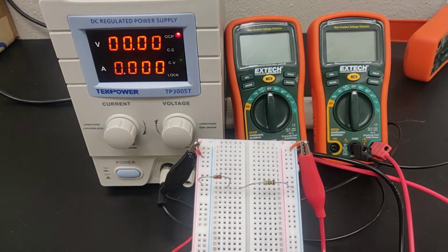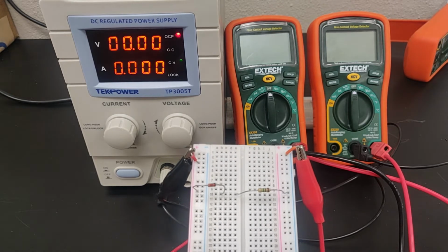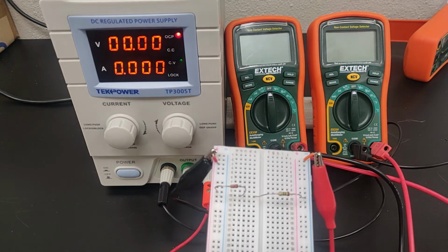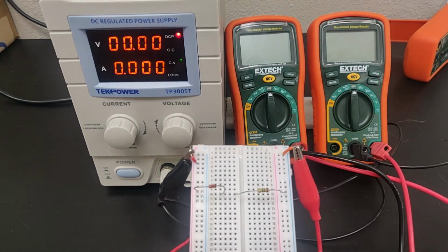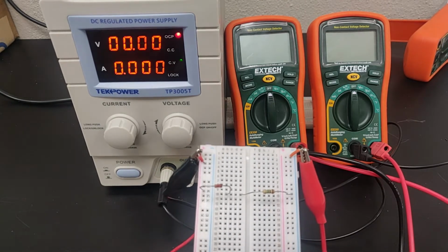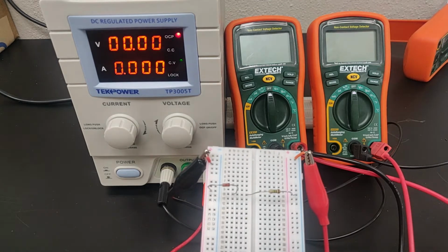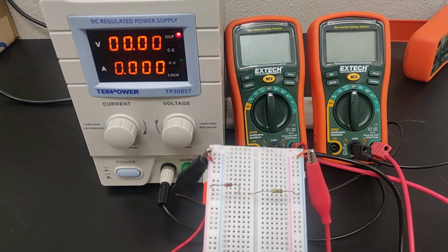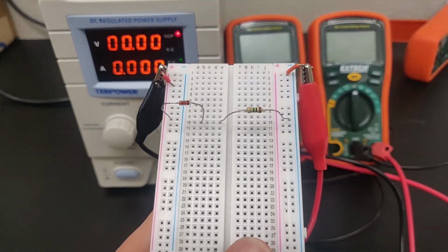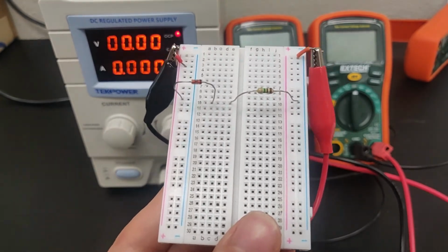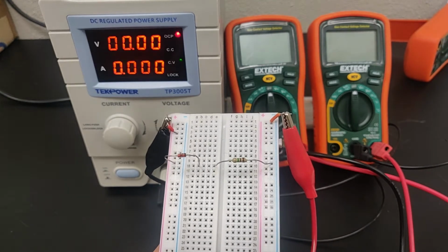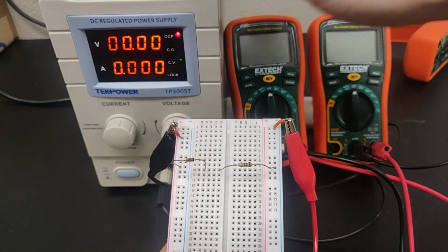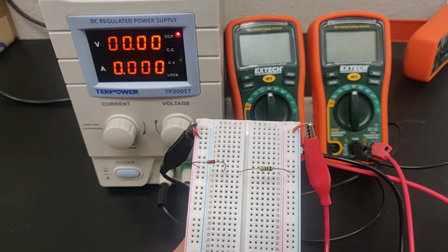Okay, so for this set of measurements, when you have a diode in this reverse bias orientation, it doesn't want current to flow through our diode. So the voltage drop over our diode is going to be very small until it reaches some breaking point and current just freely flows. And the problem with that is that it actually will break our diode. So we don't actually want to reach that point. And the voltage that we'll need to supply in order to do that would be big, like 50 volts. So we're never going to get there.